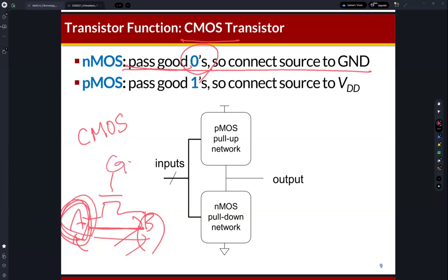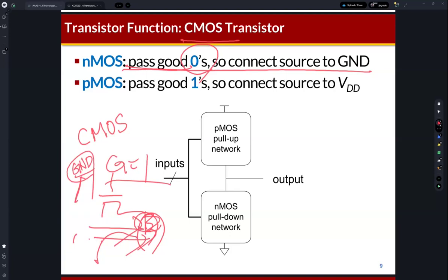Which means that when the gate becomes 1, the value of A is transferred to B. But the problem is that if the A value is ground, a low voltage, then B can also be ground, clearly. Do you understand? The voltage level of A is low, so it's ground level, and the gate becomes 1. So B is connected to A, and the value at node A is delivered to node B. If A is 0, then B becomes 0, clearly.